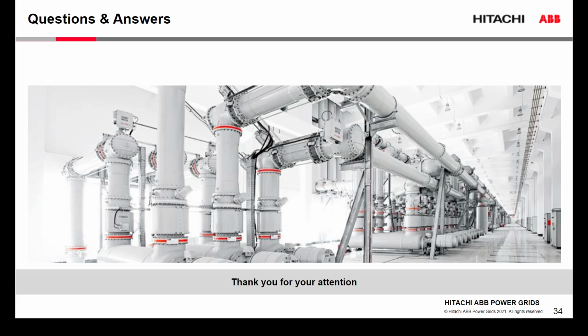So we would recommend, and that was also part of the requirement, if your future extensions are planned, automatically bring that into the design stage, and we can integrate such ideas into the overall layout of a substation to avoid shutdown of feeders or main busbars during extensions. Yes.